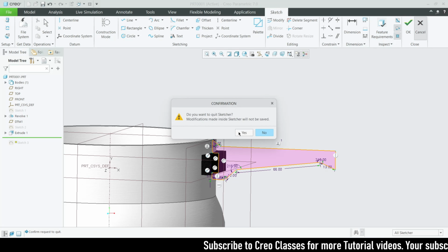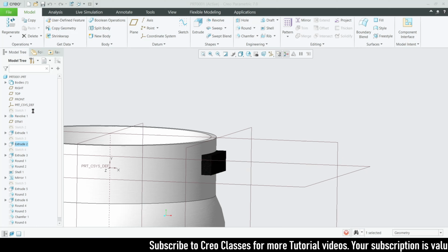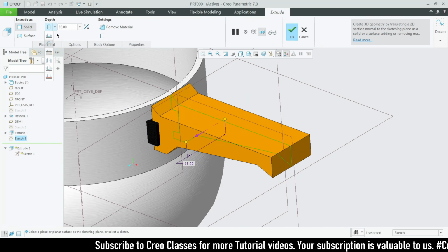Okay, so once you have completed the sketch, go for the extrude, and the extrude length is 35 as a symmetric extrude here.